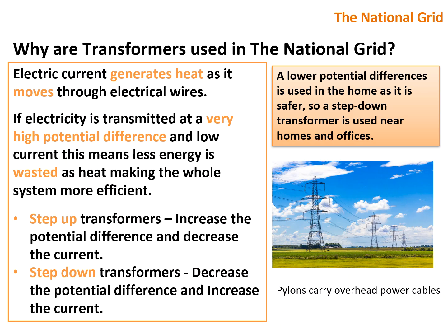And last slide, why do we use transformers? If you remember the equation, power equals volts times current. Because we send it at a really high voltage around the country, we can send it at a low current, and the lower the current, the less electricity is wasted.